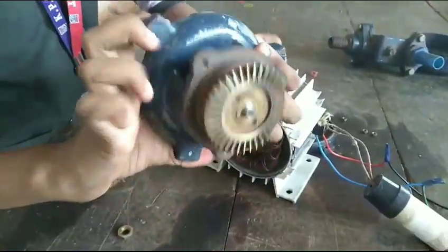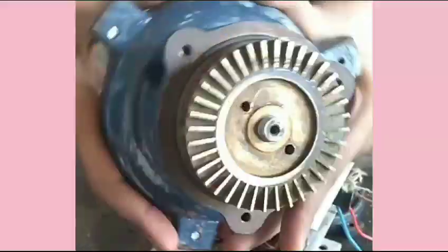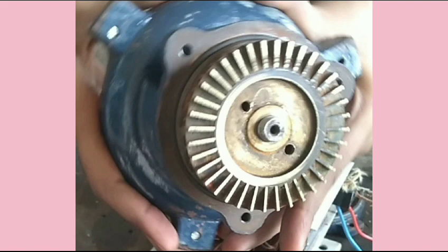An impeller is a rotating disc with vanes in a pump. It transfers energy from the motor that drives the pump to the fluid being pumped by accelerating the fluid radially outwards from the center of rotation. This means the action of the impeller increases the fluid's velocity and pressure and directs it towards the pump outlet.